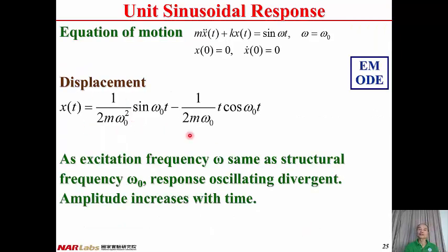And here's the displacement. As the excitation frequency omega equal to the structural frequency omega 0, resonance happens, and the response oscillates and diverges, and the amplitude of the vibration increases with time. As t tends to infinity, the amplitude of the displacement also tends to infinity. Therefore, the structure is unstable.